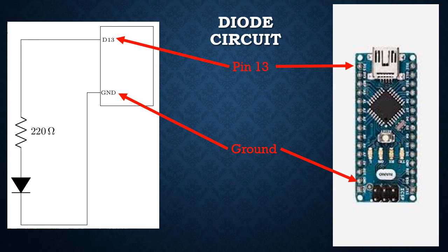Choose one of the diodes from your kit, and you want to connect that one to the lower end of the resistor. You choose a hole that is in the same row as the lower end of the resistor. Put the long leg of the diode in, and then put the short leg of the diode into yet another row.